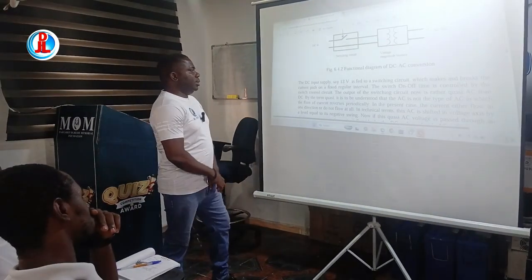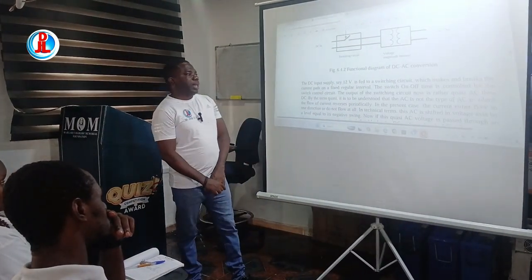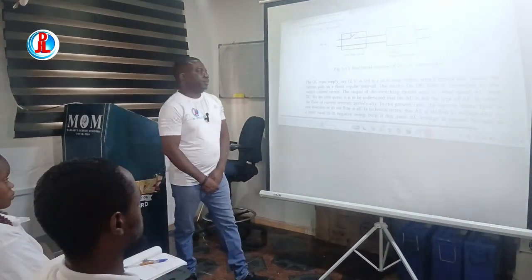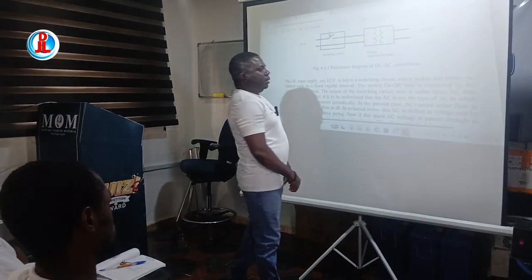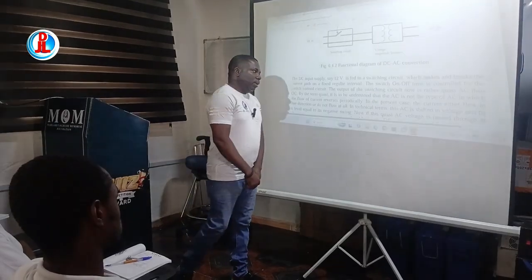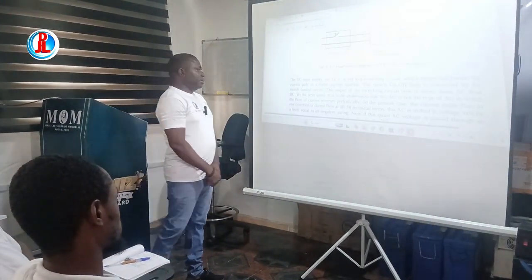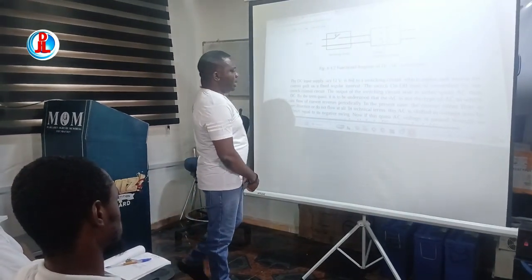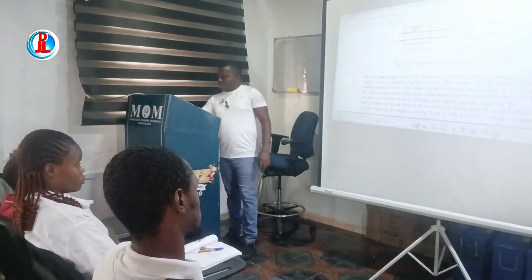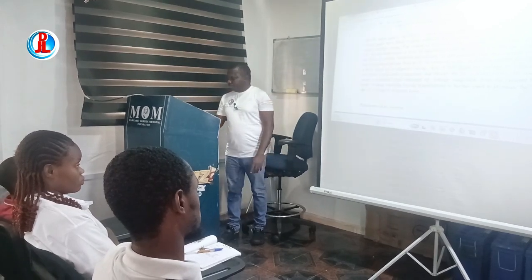By the term quasi is to be understood that the AC is not the type of AC in which the flow of current reverses periodically. In the present case, the current either flows in one direction or does not flow at all. In technical terms, this AC is shifted in the voltage axis by a level equal to its negative swing. I think some of us will not understand this angle. You need to be technical to understand, but that is exactly what I've explained.